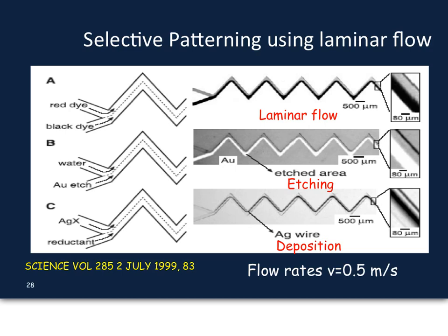But something perhaps more useful is that they can actually do chemical etching or wire deposition using this technique, where they put two chemicals side by side flowing through this channel, and they react, of course, only on their surface. Then they can deposit, for example, a wire electrode on the bottom of the microfluidic channel that is very small and exists only at the interface of those two chemicals. Equivalently, they could also etch only a very specific area if they'd like to do that. So this technology could potentially be used as just another degree of freedom in lithography and photolithography.